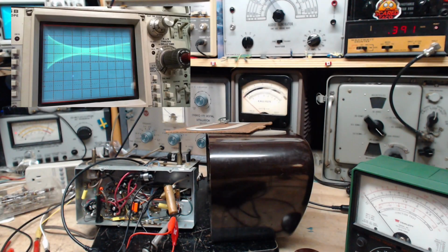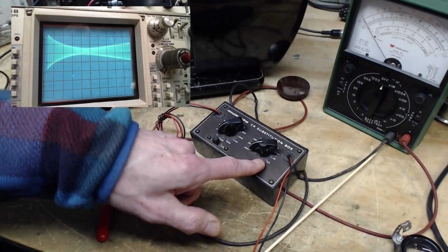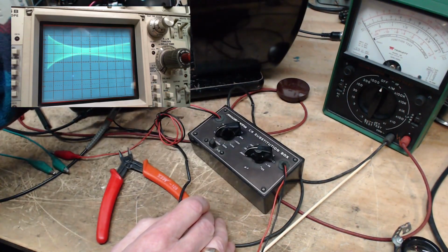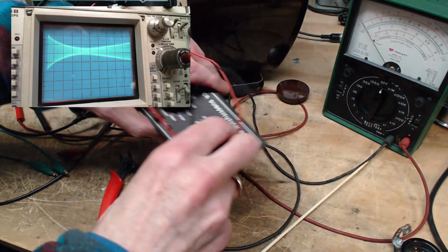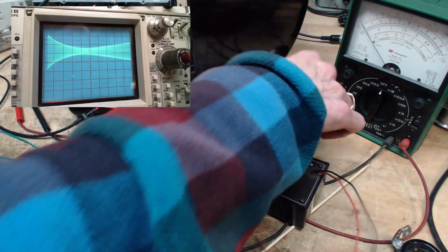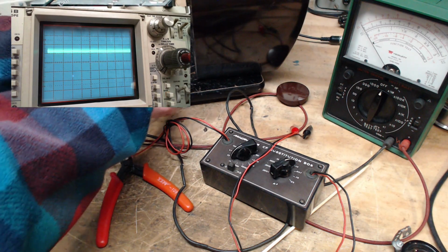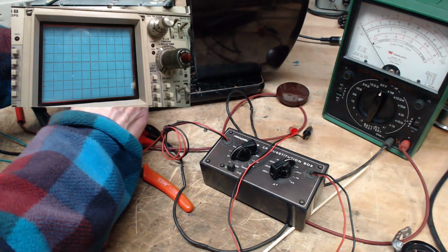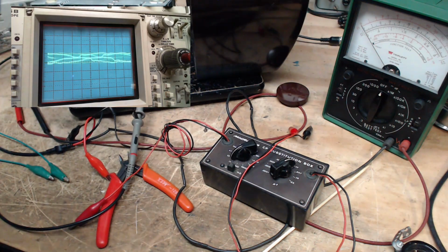Okay, got an idea. I have a substitution box right here. And the substitution size goes up to 0.2, which is a fairly large capacitor, similar in size to this. Why don't I put this box in, adjust the size, and see what happens? Try different sizes with the radio operating. So in order to do that, I gotta remove all this stuff. Everybody off. Okay, everybody's off.